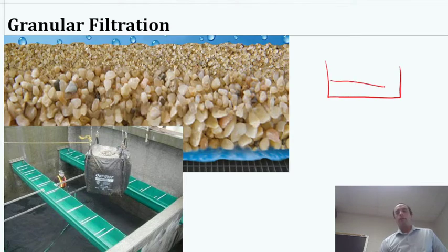You have some media, and then you stack up the water on top of the media, which then the gravity by itself is exerting some force pushing it down through the granular media. So in either case, you're getting the same effect. With the column systems, you can usually have a little bit higher production rates, just simply because your sand is confined a little better, and that added pressure is not going to cause as much problems as it would in an open bed like this.